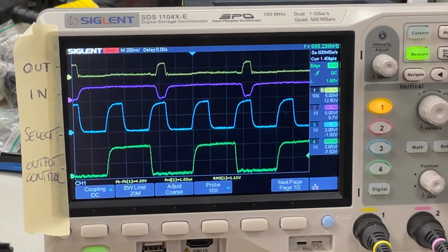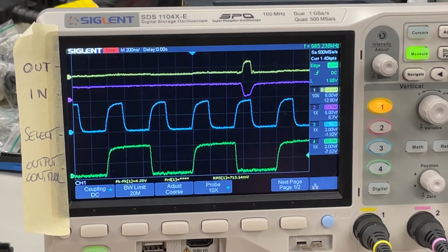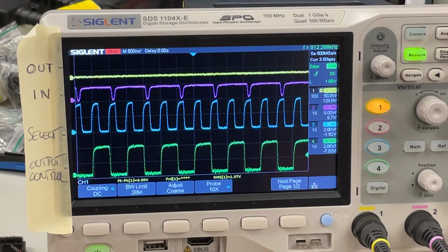So I don't see an anomaly here, but again, the other C64 is even refusing to start, and it has that weird waveform on a line which is basically looped inside the same chip. So there's nothing around that can affect that one, to be honest. So I feel there's something wrong with this chip, and I want to replace it and see if this time I got the right one.